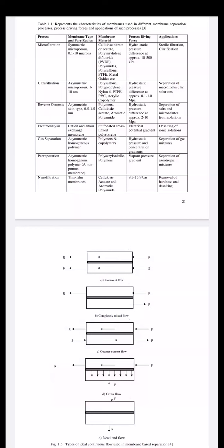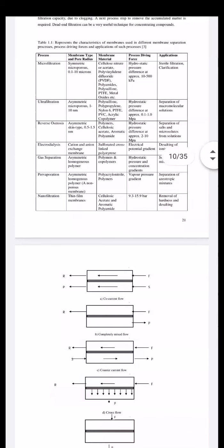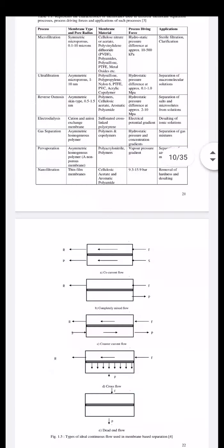Generally the density of gases is very low, which is why it is not that essential to worry about the thickness of the membrane. As per the driving force, the hydrostatic pressure and the concentration gradient, which is generally used for mass transfer, are used, and the separation of gas mixtures can be achieved as an application by using such membranes.